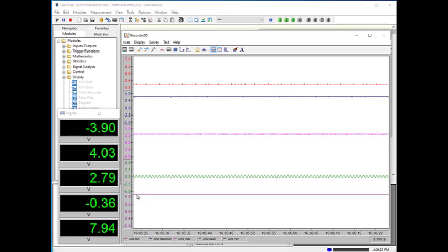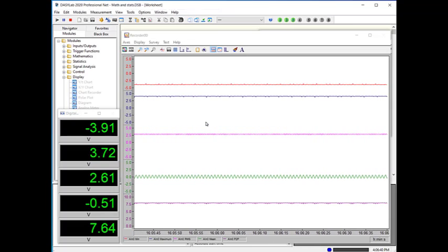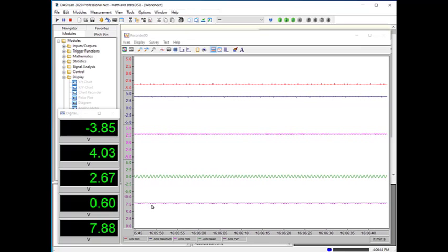I'm not able to see it on the chart, so I went back to multiple charts to see what the problem was, and the problem was the range. This is 7.9, so I am going to change the range from 0 to 10 to be able to see the peak to peak. So the peak to peak is staying right about 7.9. So the minima, the maxima, the RMS, and the mean.